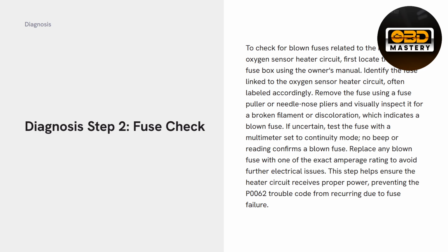Usually needle nose pliers are a little bit more convenient as they provide you with a little bit more give, so you can actually pull it out, but just visually inspect it for a broken filament or discoloration, which indicates a blown fuse. Now, if you're uncertain, test the fuse with the multimeter set to continuity mode. No beep or reading confirms a blown fuse, and replace any blown fuse with one of the exact amperage rating to avoid any further electrical issues.